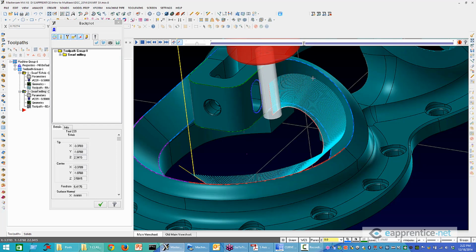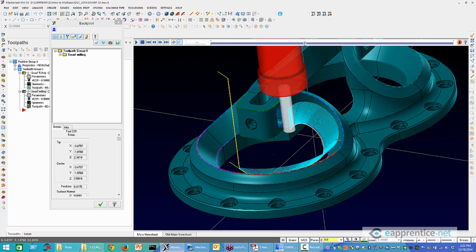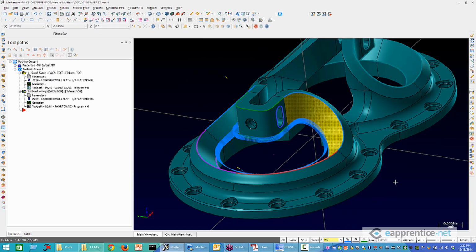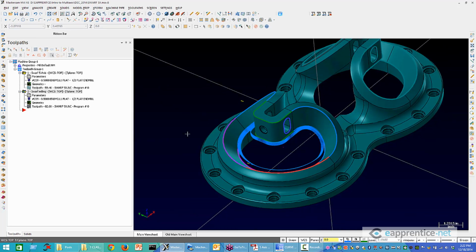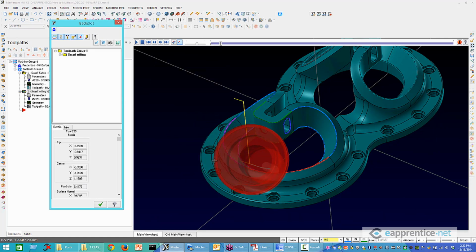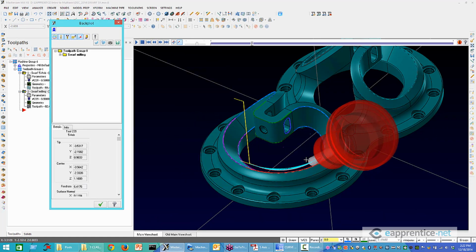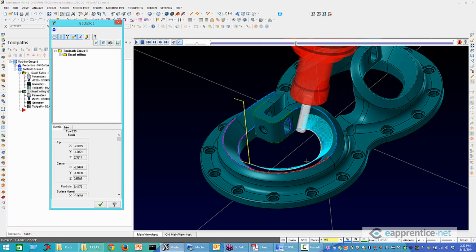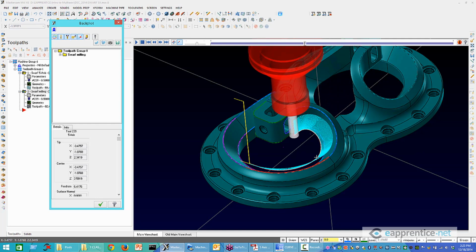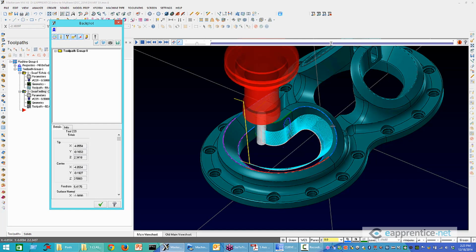So that will produce, now there's still going to be, if this is a convex surface, a little bit of excess material that may not exactly match the model geometry, right? But it's going to be hopefully close enough, hopefully within your tolerances, because taking a tool and running around a feature like this to finish it is going to be much more efficient than if we were just going to take a ball end mill and try to surface machine that piece right there.